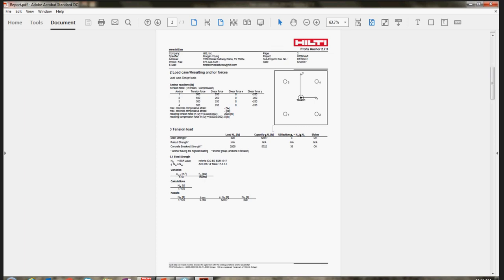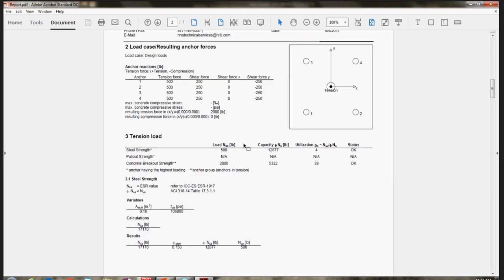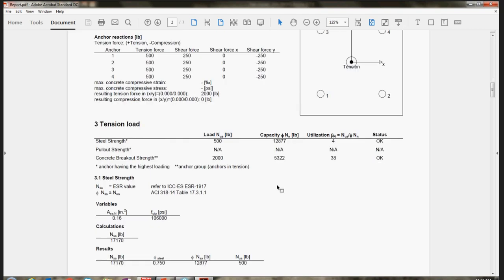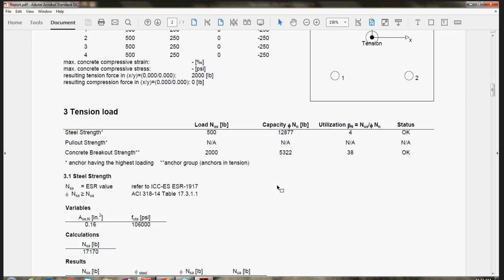So I'll go ahead and click on the anchor spacing dimensions first, and I will hit the value and hit enter. So here I'm going to change our anchor spacing to 6 inches, both symmetrical. And now the second thing I'm going to change is my base plate spacing. So this base plate is going to be 10 inches by 10 inches. So I'm going to make these changes here as well. I'm going to zoom in some more. And now I'm going to change the fixed edge dimensions. We're going to have a 4-inch fixed edge as well as an 8-inch fixed edge. Again, zooming in for clarity.